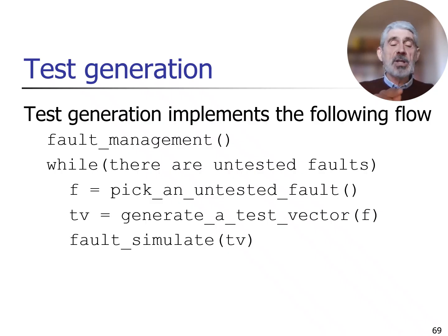For this purpose, I will activate a fault simulation step in which all the faults which are also detected by the same test vector TV are marked as detected, or tested.